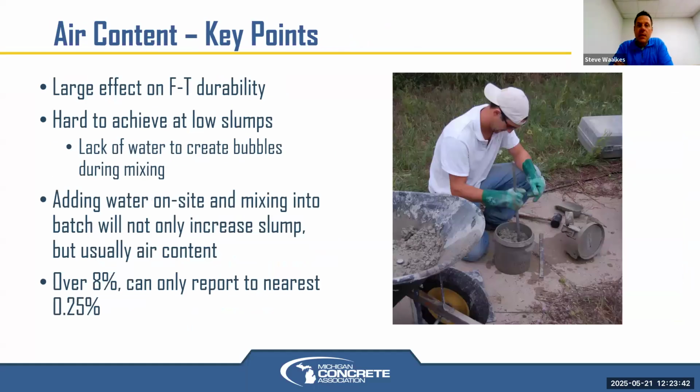So, all right, air content. Here is a pressure meter being filled, probably on layer number 2 out of 3. Air content is minute microscopic air bubbles, closely spaced, spread throughout the paste, the cement that's in the concrete. That is what gives us freeze-thaw durability in our harsh freeze-thaw environments here in Michigan.